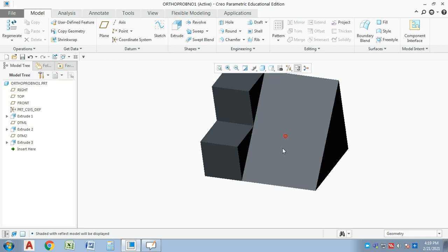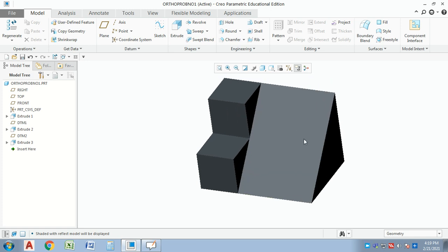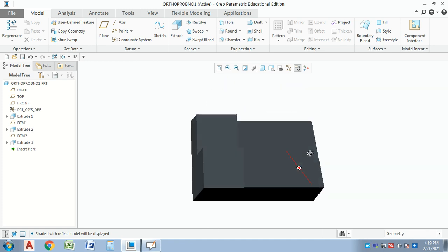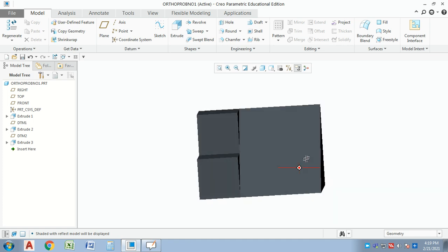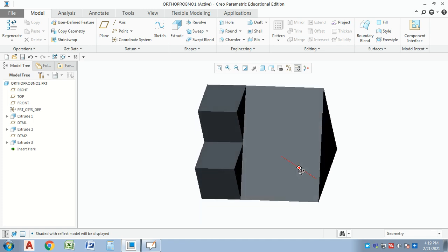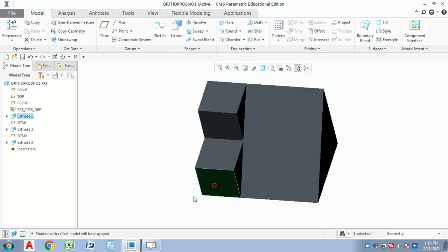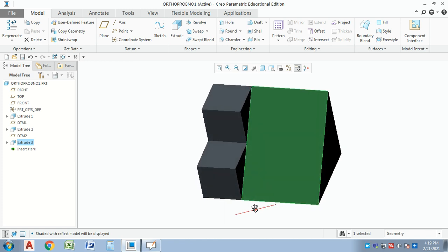If you see this, what they said, from this direction it is a front view. Now see, if you look perpendicularly at this object, we will get the exact front view. Okay, so this face is visible in front view, this face is visible in front view, and this face. Now as this face is a slanting, inclined surface, it will be visible from top view and front view.